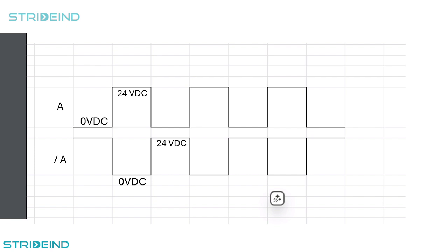If one of your channels is broken, you may not get this voltage, and if you start moving the encoder, you will see this 24 volt invert and come back. You can see negative 24 or positive 24. These are very sensitive. You can't always identify them, but slow movements can give you this positive negative shifting. That's how you can identify that your channels are okay and giving feedback. It doesn't guarantee it's going to work, but at least you are sure that no wire break has happened.